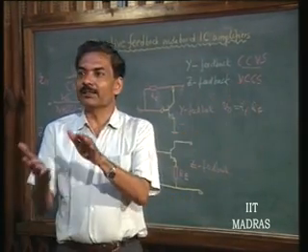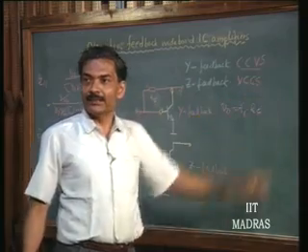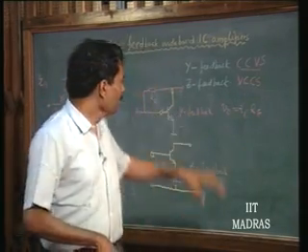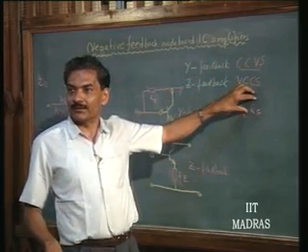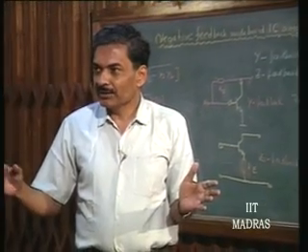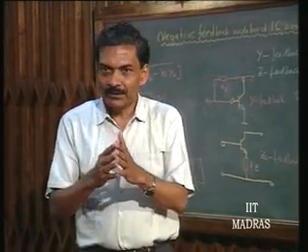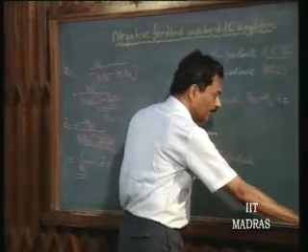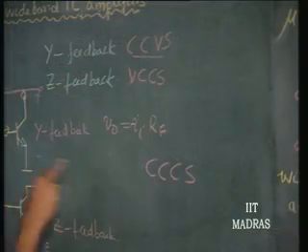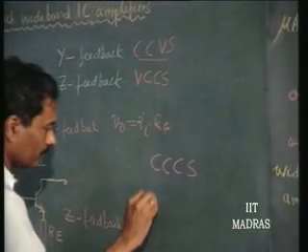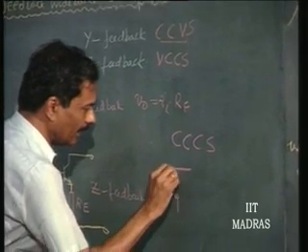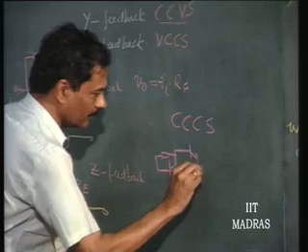Voltage control means it is open circuit. A voltage source means a source impedance of 0 magnitude, right? And therefore there is gross mismatch of impedances, and therefore it retains the wideband nature. So now I can cascade these two together and result in a current controlled current source. How do I do it? I put Y feedback first, then I cascade the Z feedback.